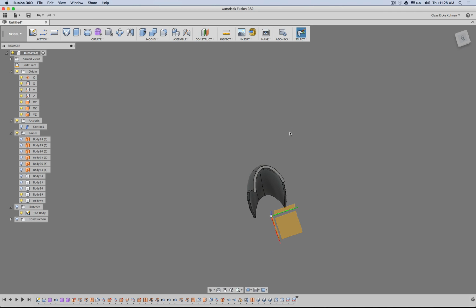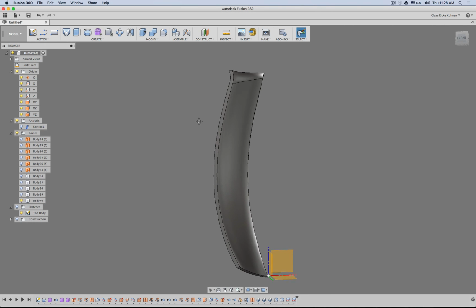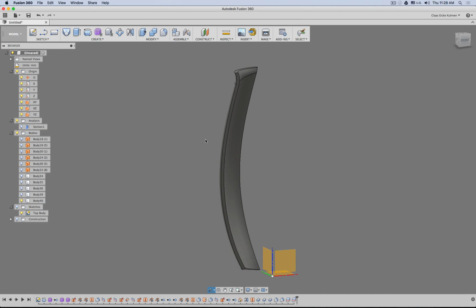We want to have a nice surface on the outside. So the inside, the hollow area, will be filled with support. And we could maybe even use the support area as a glue surface. Plus, if we have 2 millimeters, we have an area where we could put super glue down, and then we just glue these two parts together.